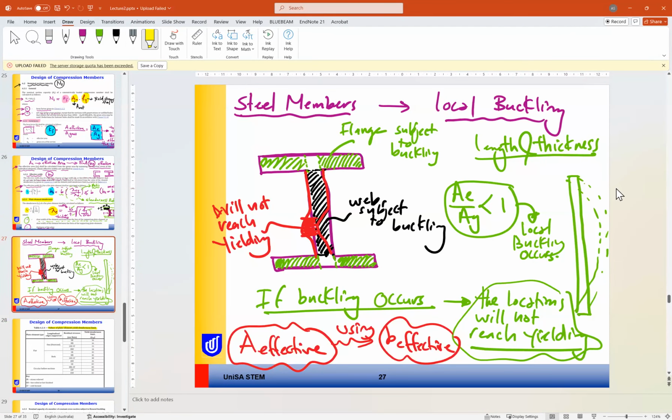Yes. So I'm a bit confused why that shared point between the flange and the web is not considered in buckling, is it? Yeah, because buckling means the free part of the member that can deform. But this part, you mean this part, right? Yes. This part cannot deform because it is connected together. So this part of the flange, the free part, can deform, deflect and buckle. But the yellow part here cannot move because it is connected to each other. Okay, thank you.